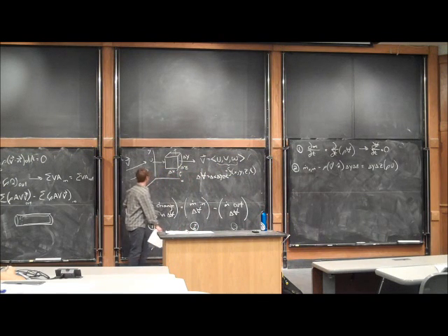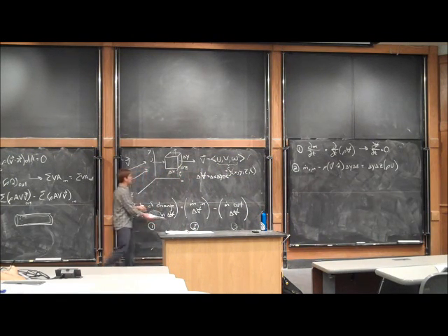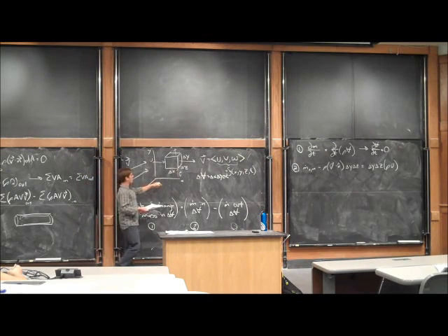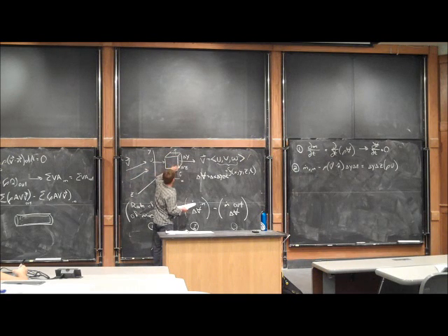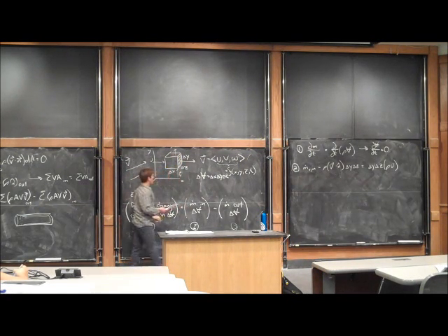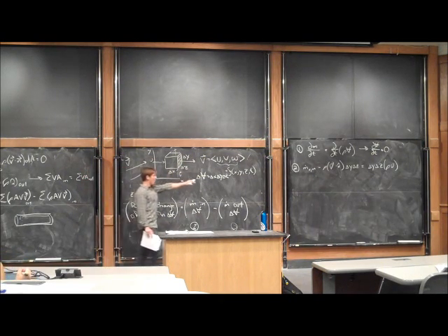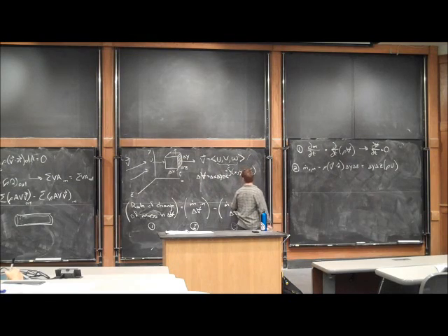If we just imagine that all the flow is only going in the x direction, the flow going through this cube would be the velocity in the x direction, u, times this area. That area times velocity is our volumetric flow, times rho is where we get our mass flow in the x direction through that cube.